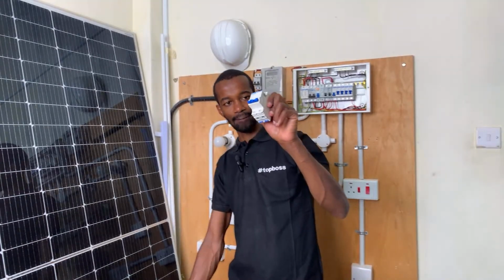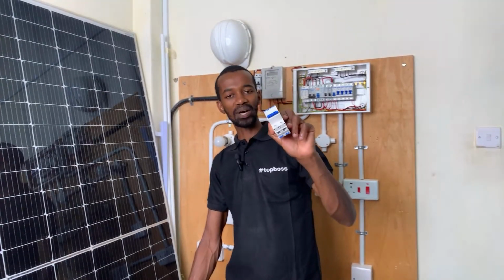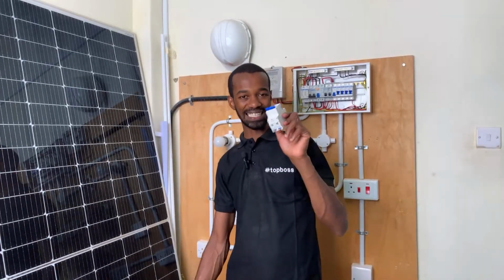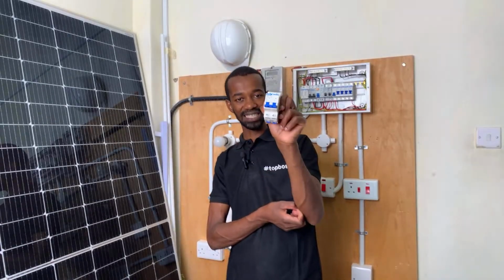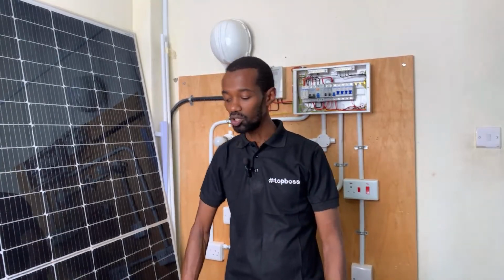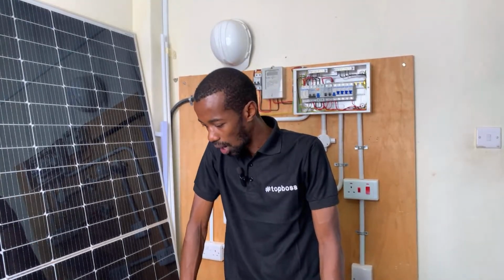Assuming that there is a huge short circuit that is happening, huge in this case, more than 63, the sole purpose of an MCB is to detect that the current drawn from it is above its rating, and then it trips, shutting down the supply of electricity in that installation. So assuming that in a home which is using a 63 ampere MCB, there is a short circuit or an overcurrent.